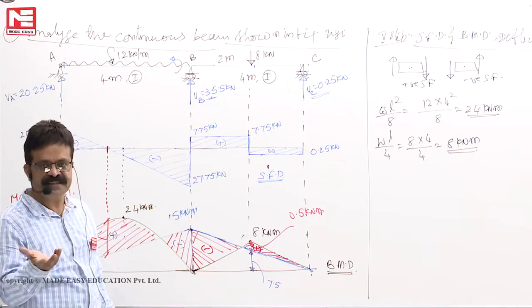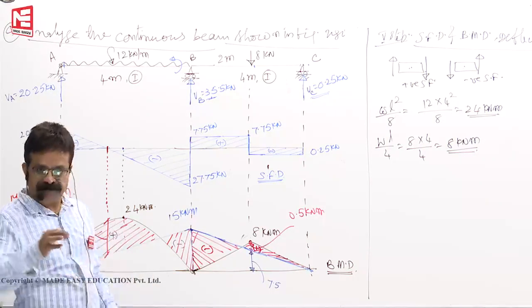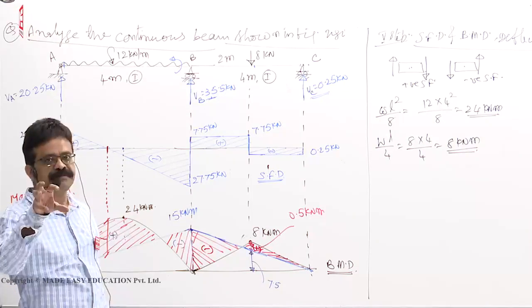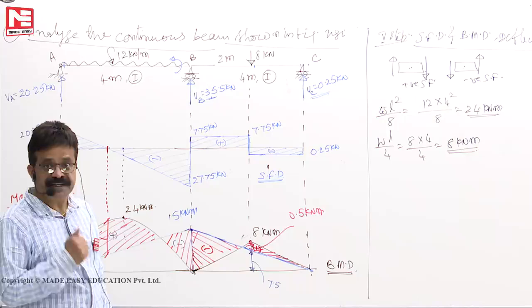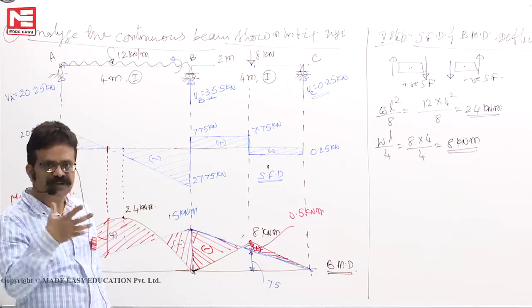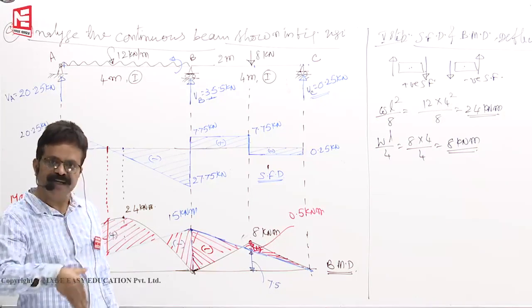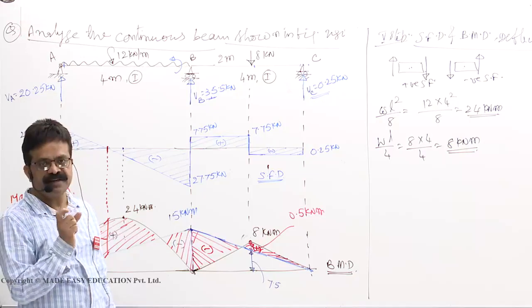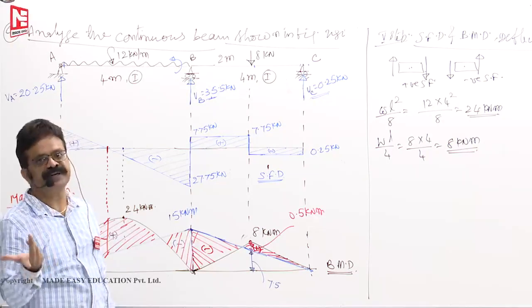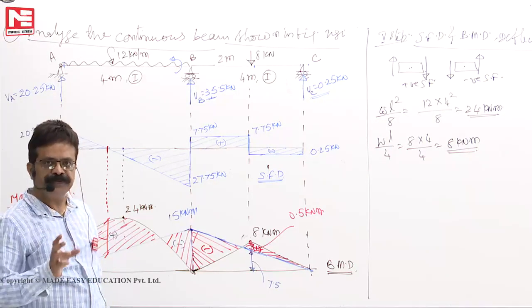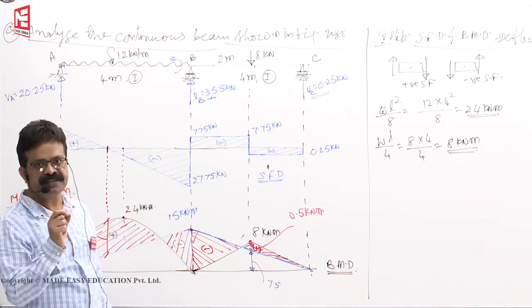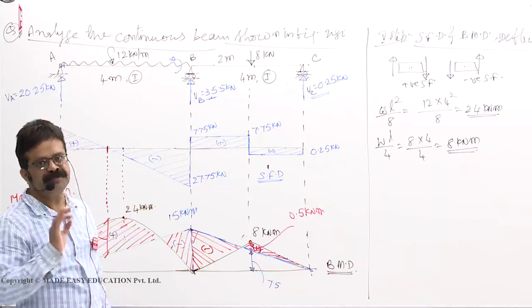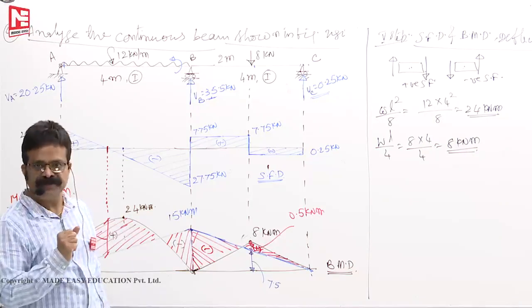Positive means tensile stress, negative means compressive stress. Mathematically, if you see 0 stress, major principal stress is 0, minor principal stress is minus 20. Then with 0 it will not fail, it will fail because of minor stress, means minus 20 Newton per mm square it can fail. So it is not necessary that an element fails because of major stress. It can fail by minimum stress also, mathematical minimum value.